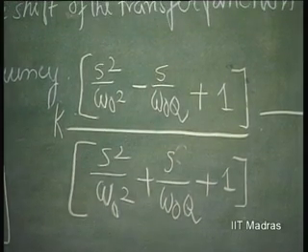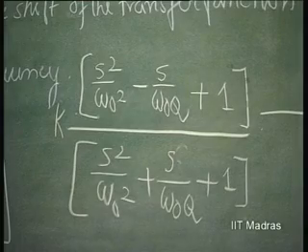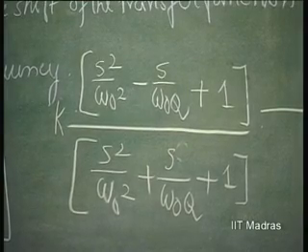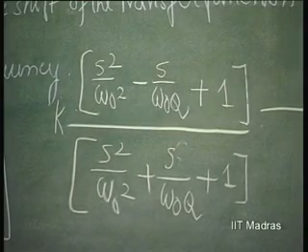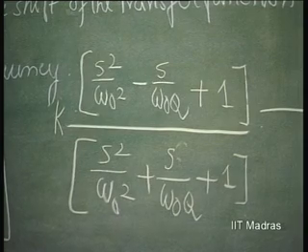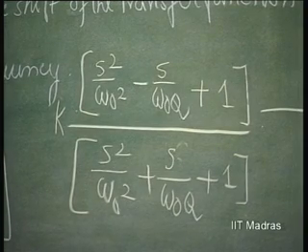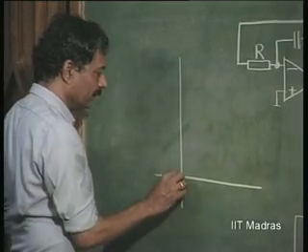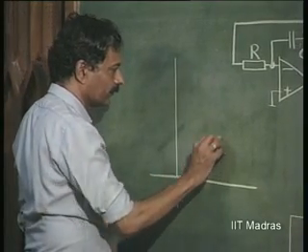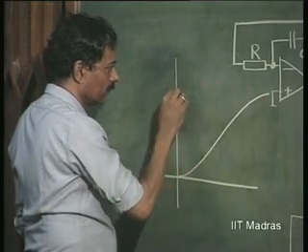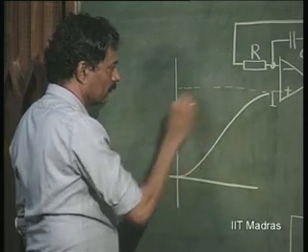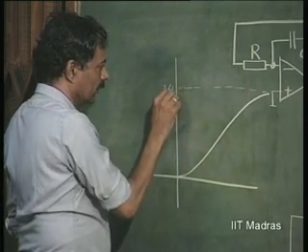and the addition of the zero will contribute another 180 degrees. So, the nature of variation of this phase with respect to frequency is the same both for poles and zeros, because the coefficients are the same, and therefore, you will see that the phase shift varies all the way from 0 to 360 degrees.